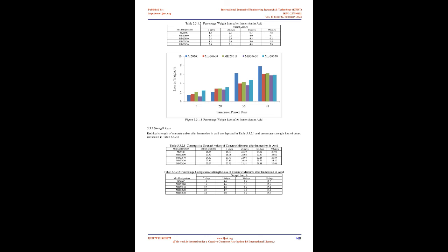4.3 Flexural Strength. The flexural strength is expressed as modulus of rupture in MPa, which represents the maximum stress at the extreme fibers in bending. This test is carried out on 100 mm x 100 mm x 500 mm prisms subjected to 2-point loading as per IS 516-1959.